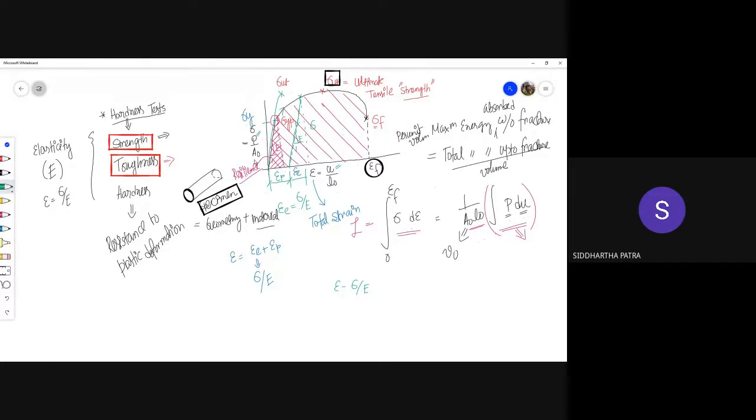You can of course have the dimensions, the cross section area and the length, all pre-measured before the experiment. These are the original cross section area and the length, and so you can calculate the engineering stress and strain, and you have the stress strain data.